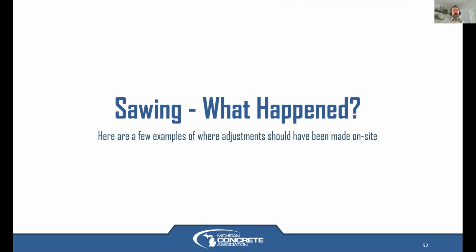Yes. In general, the issue with MDOT's standard expansion paper historically was 1 inch. I believe they still have that as an option. I don't know if they have the 1/2 inch option, but that fairly thick asphalt impregnated fiberboard can close up significantly over time, which means that all the joints beyond that, away from that expansion joint in both directions, are now opening up.